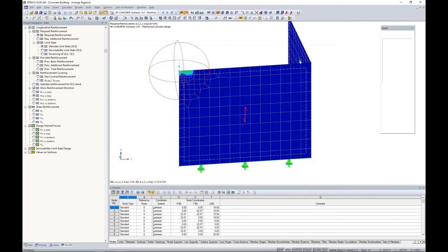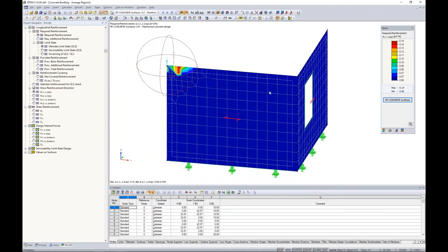Now, lastly, we can view this information graphically again, and we can take a look at the required reinforcement in the different directions. Now, by all means, we still have these areas which have higher internal forces, which is fine. This probably stems from our rib and our panels framing into it behind this particular wall. But we're not looking at 0.95 inches squared per foot. Again, we're looking at the max of 0.3 inches squared per foot. So that is much more realistic.